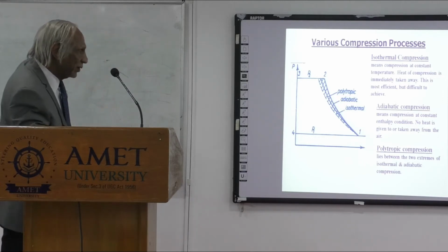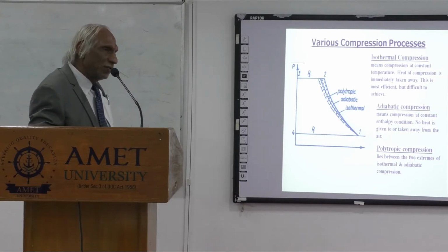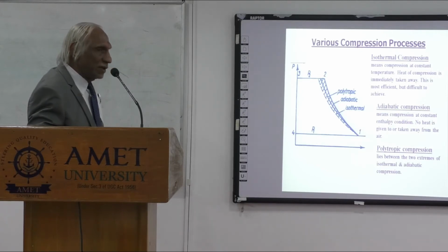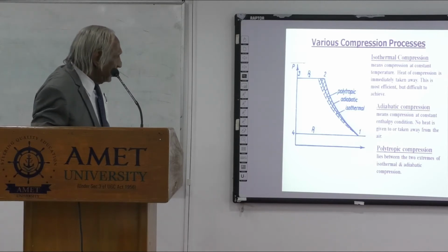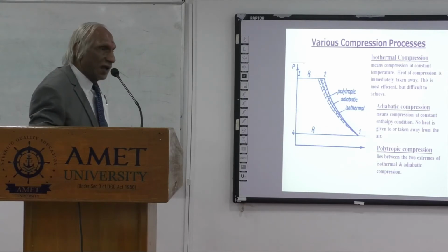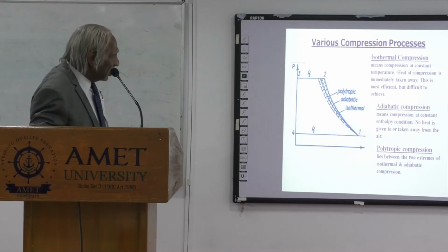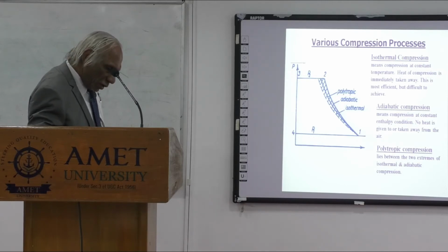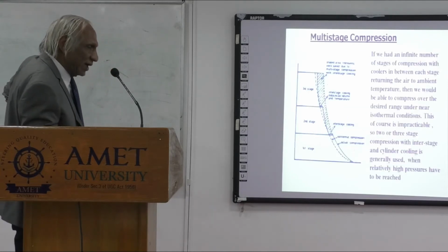So therefore, the compressor, which is a power taker, will not absorb too much power from the electric motor driving the compressor, or some other prime mover like a diesel engine. The idea is that the work input required for the compressor should be kept as low as possible. So your objective should be to follow the compression curve as close as possible to the isothermal condition.